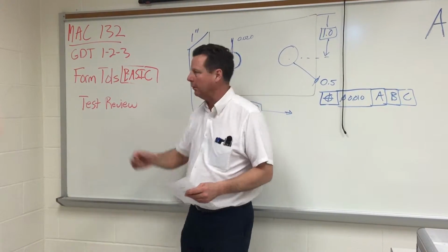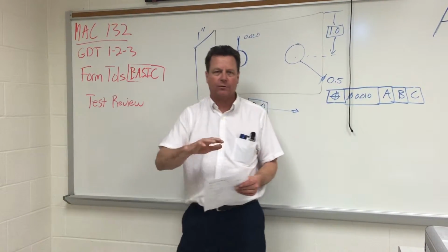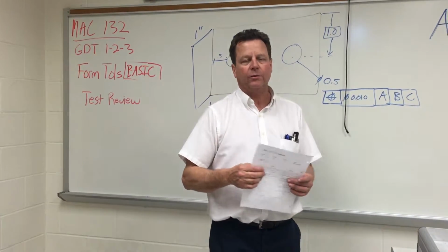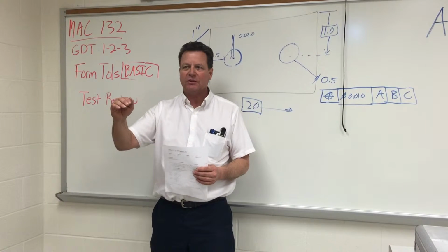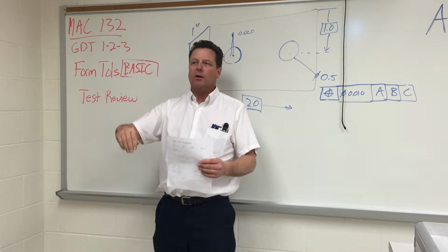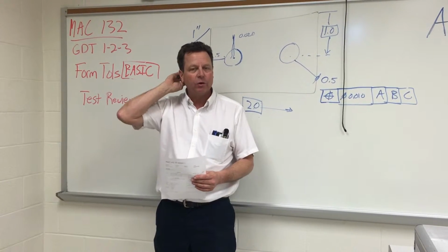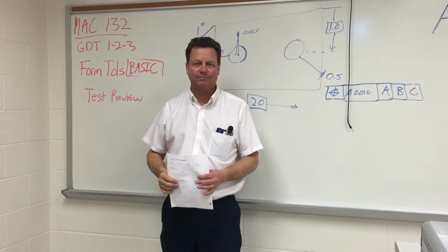What did we learn today? Well, we reviewed GD&T 1, 2, 3, the basics of GD&T. GD&T 1, 2, 3 refers to establish the datums, then control the datums on the part, and then locate the rest of your features to the datums.